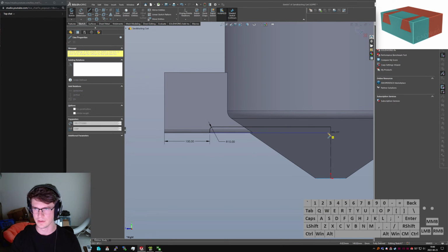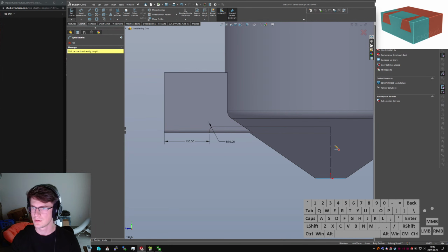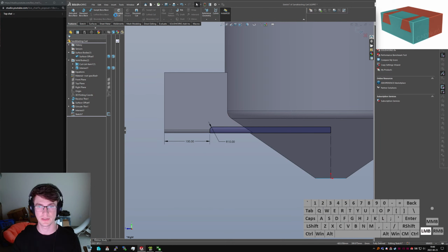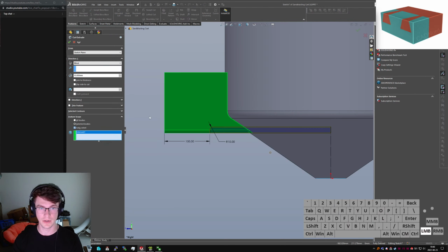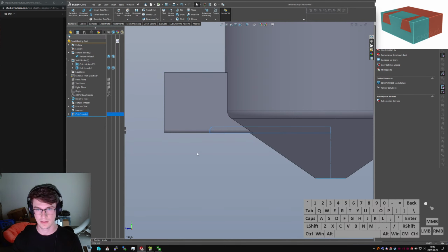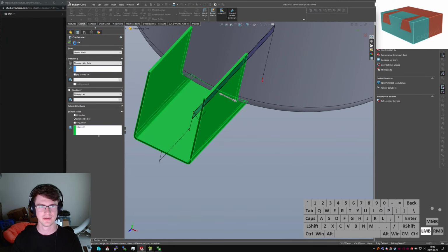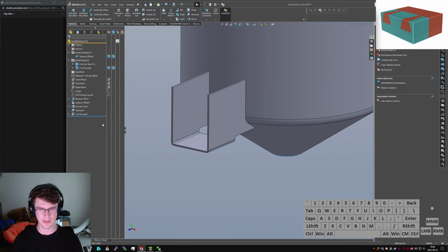And then for safety, I am going to add a split line here and then use this as a single continuous, so it's a closed section. So it's a little safer cut rather than removing potentially unwanted parts of the body. And I just realized I made that blind, which will have the nice fun effect of doing not much. If we do through all both, it'll cut what I want. There we go. Selected bodies are all accurate.